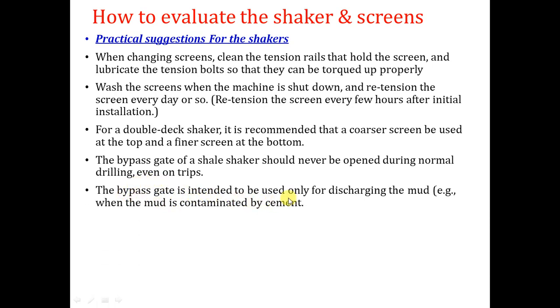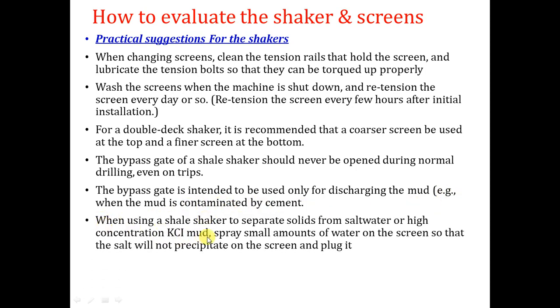The bypass is intended to be used only for discharging the mud when it is contaminated with cement. When using a shale shaker to separate solids from salt water or high concentration KCl, spray a small amount of water on the screen so that the salt will not precipitate on the screen and plug it.